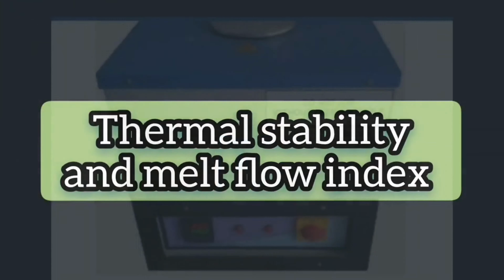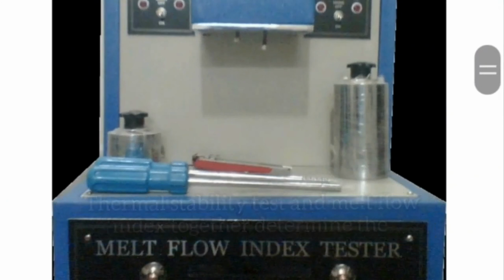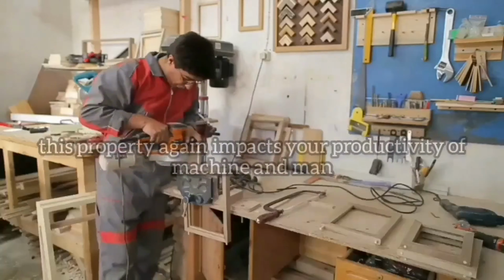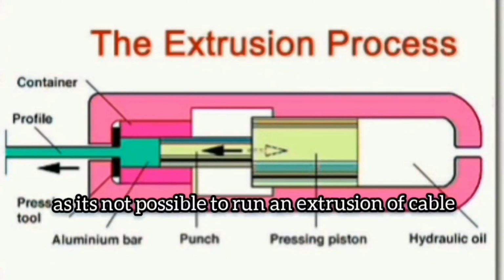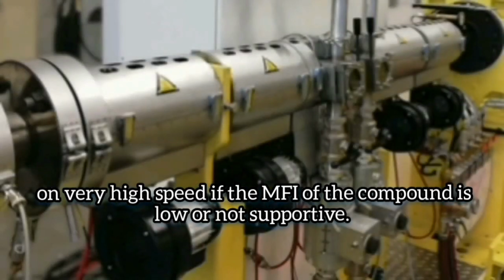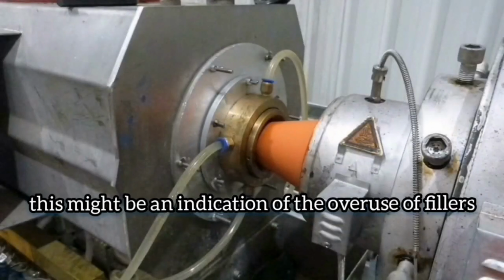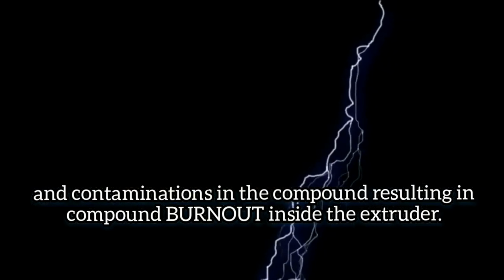Thermal stability and melt flow index: the thermal stability test and melt flow index together determine the temperature profile of extrusion and also the speed of extrusion. This property again impacts your productivity of machine and man, as it's not possible to run an extrusion of cable at very high speed if the MFI of the compound is low or not supportive. Similarly, if the thermal stability of a compound is not according to norms, this might be an indication of the overuse of fillers and contaminations in the compound, resulting in compound burnout inside the extruder.